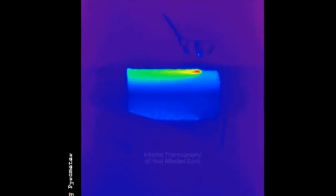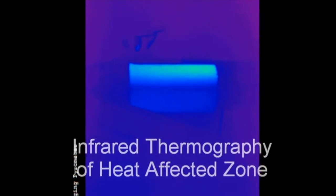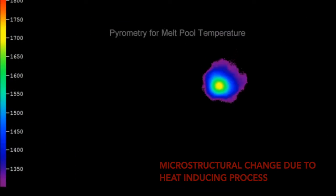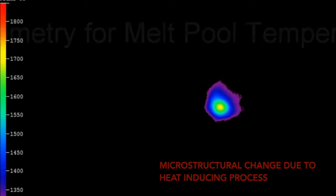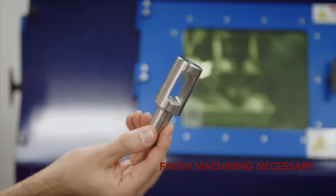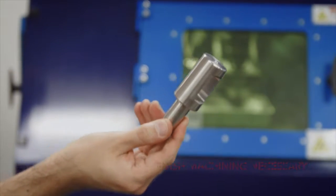As can be seen in the infrared thermography of the heat affected zone, the temperature in the focus point of the laser reaches up to 1900 degrees centigrade. This can result in a deformation of the crystalline structure of the metal, depending on the used powder material. Due to the poor surface roughness of 12 to 25 micrometers Ra, a surface finish is needed for the manufactured parts.